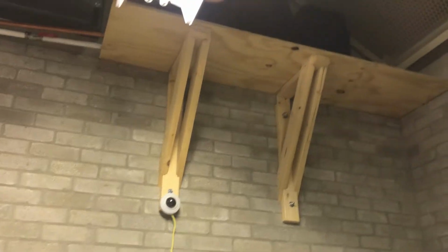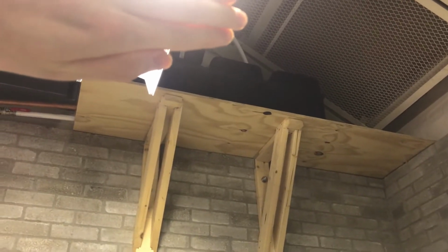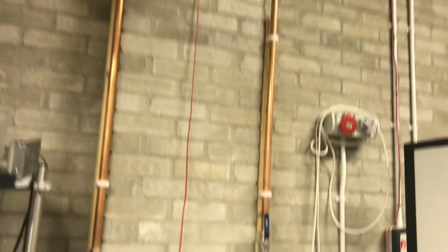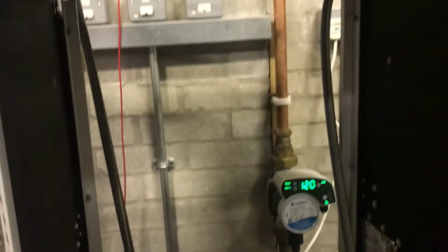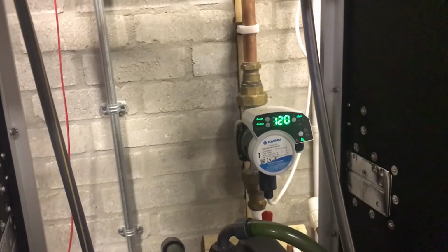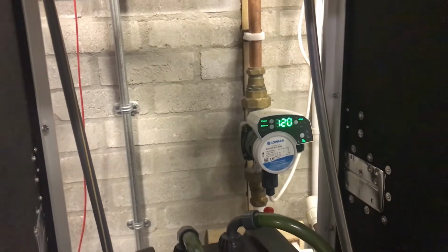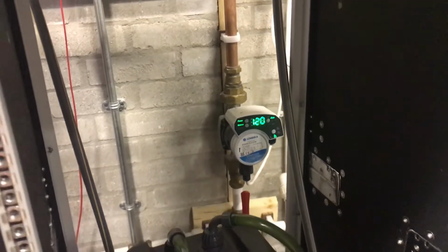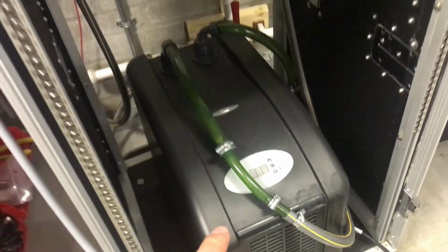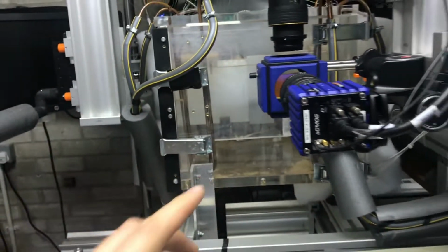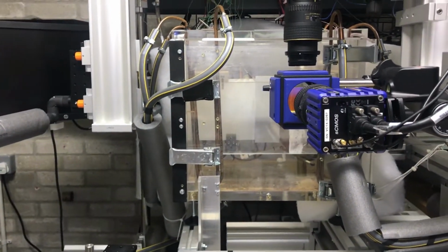If I block out the light, you might be able to see it. So the tank there, and that's actually running around here, coming across, and then coming down to a pump which is at the back here, and at the minute it's set on very low, but that tank's getting a little bit low, and this pump goes into the chiller and is what's supplying coolant around all of these pipes. So actually the cooling system has quite a large inventory of water.